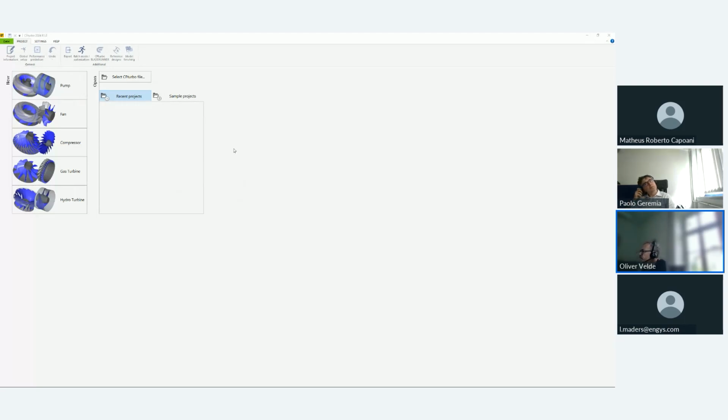Pick one of the fluids there, choose a typical reference temperature and pressure, and then you get the properties that should be used for the design. If the fluid you have chosen is described in both of these libraries, then you can also make use of the models that are used there. If it's an own defined fluid, it will be treated as a fluid with constant properties.